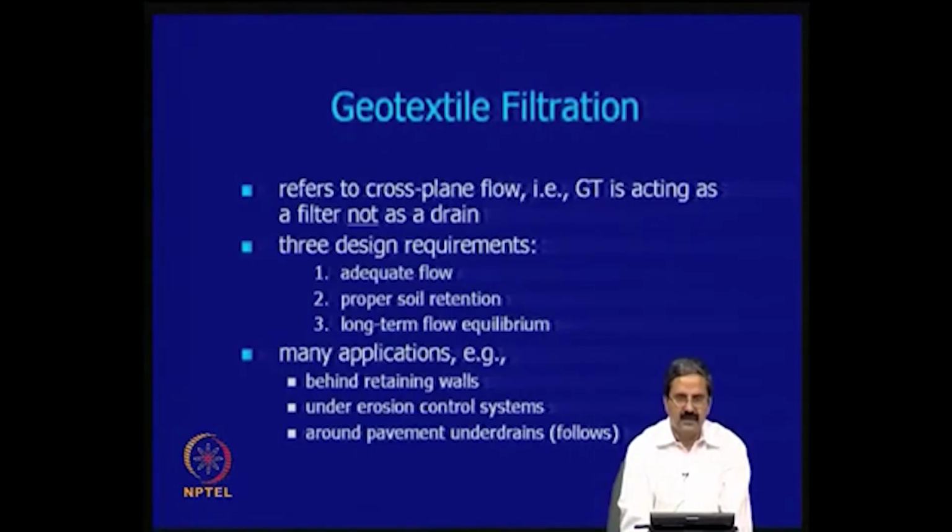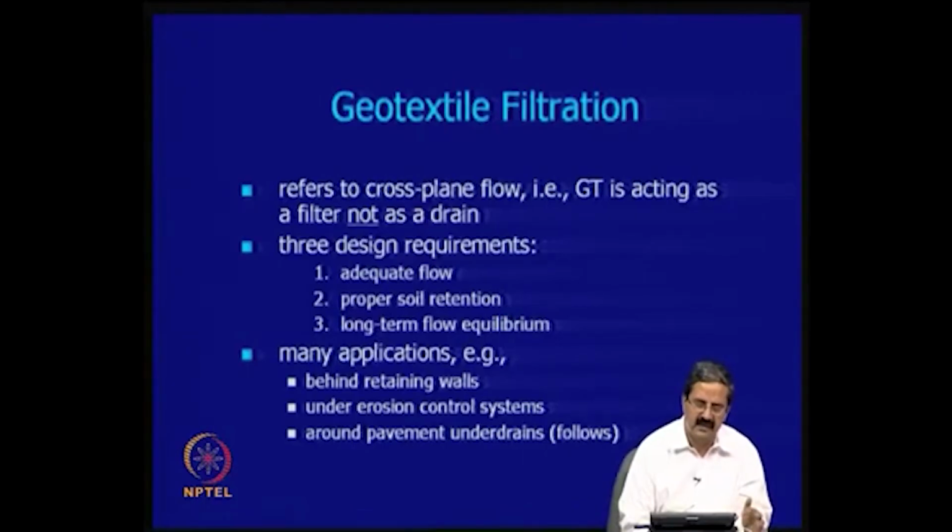But in geotextiles, that is going to happen in natural soils also. If you use gravel or sand as a filter, sand you may say is a very good filter, but over a period of time, if the clay and sand get mixed up, then there is a probability that there is not good flow in the long term. So, you put a geotextile in that place, and definitely it has a better performance.